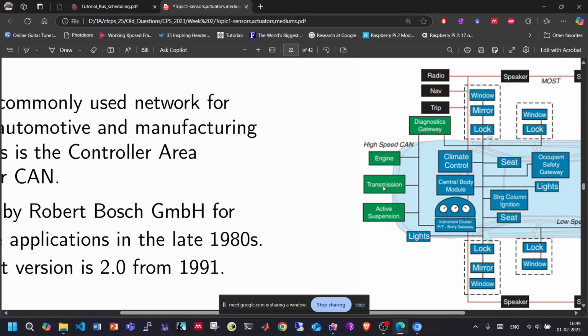As you understood. Okay. So what I am trying to say is, choosing the ID based on the importance is not the only design criteria. There are other design criteria in the system design as well. One of them is the periodicity of the signal or the sampling rate of the signal. By changing that, we can avoid the situation you just told.